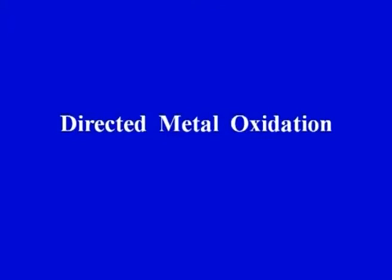So let us start our discussion for directed metal oxidation. In directed metal oxidation, three words are there: directed, metal and oxidation. Directed means that the reaction would take place in a particular direction. The reaction would be for a metal, because the word metal is in the name, and oxidation means the type of reaction would be the oxidation reaction. For example, aluminum may combine with air to form aluminum oxide. So directed metal oxidation means the direction of the reaction: the metal would be there and it would oxidize to create a reaction product.